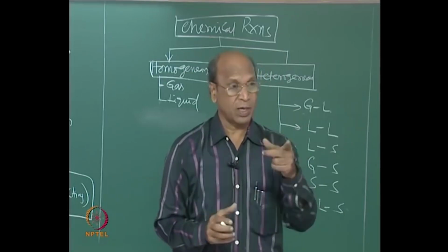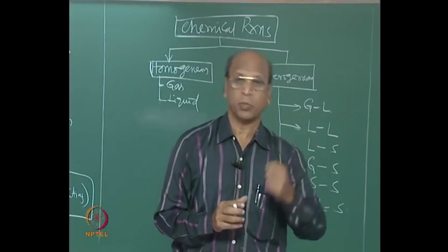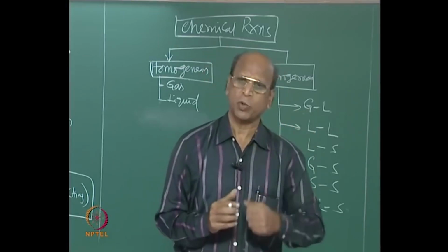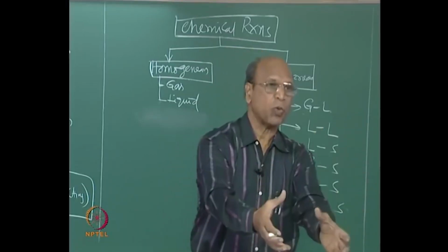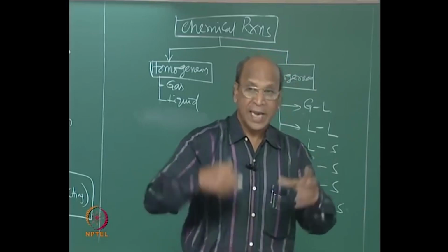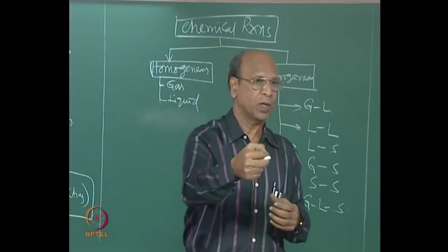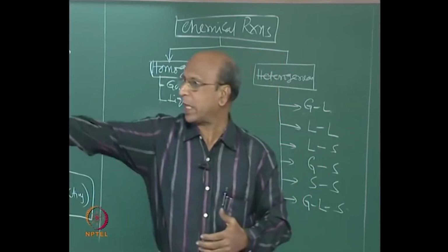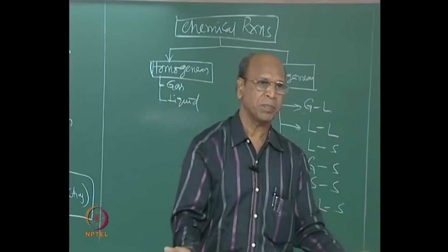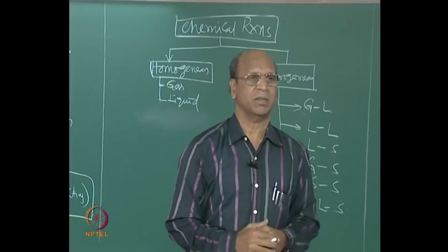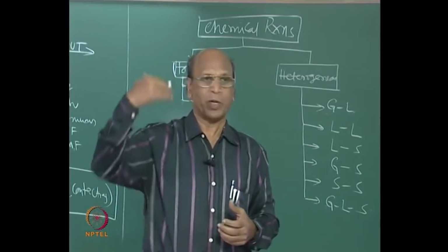That is why you heard also in thermodynamics what are called extensive properties and intensive properties. What is the beauty with intensive properties? Independent of size. That is what we want to talk about here. The rate is expressed like that, moles converted per unit time per unit volume. Then you take 10 liters, I take 5 liters, he will take 0.5 liters. All of us, when you convert per unit volume, we should get the same rate. That is the reason why we express moles per unit time per unit volume.